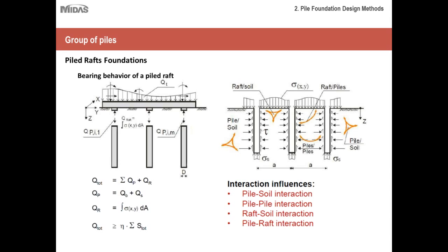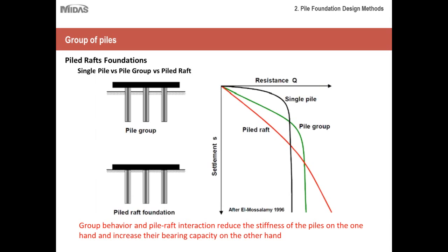As I mentioned previously, pile raft foundations can have hundreds of piles under their raft, and the cost of the foundation would definitely go up if you have too many excessive piles. So it is again strongly recommended to perform a numerical analysis in order to capture these interactions and optimize your pile raft strength and behavior.